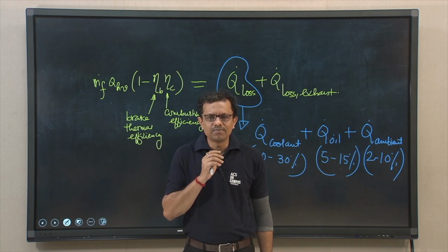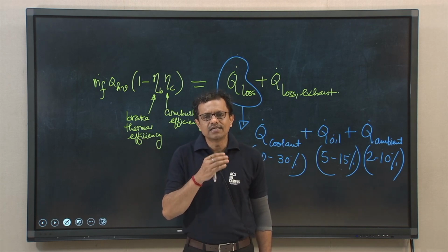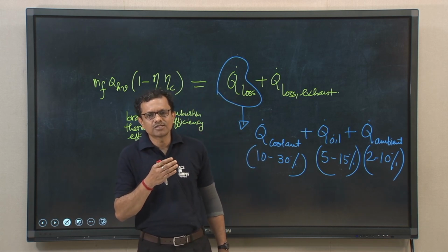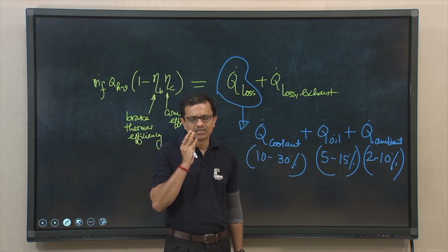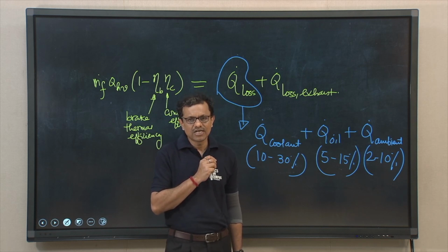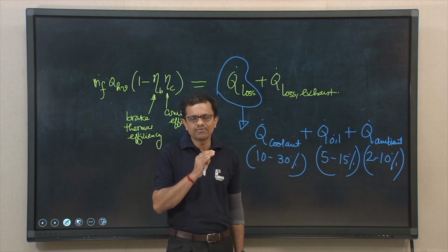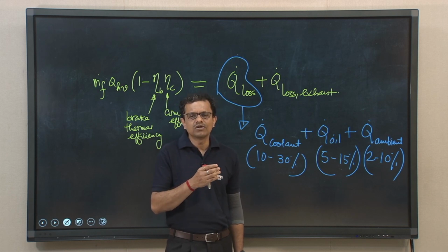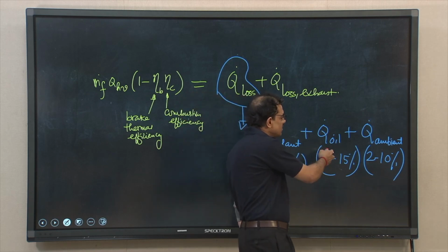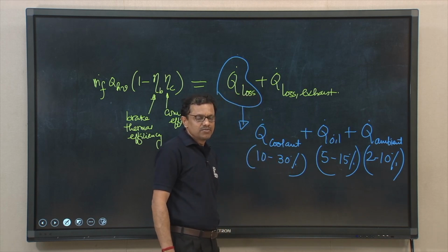In the last class we mentioned that a few surfaces or spots have high temperature: the piston face, spark plug area, exhaust valve, and to some extent the intake manifold. So the engine should have an arrangement to remove heat from the piston face so as to increase the life of the piston, and that is why lubricant oil is splashed over the piston face.